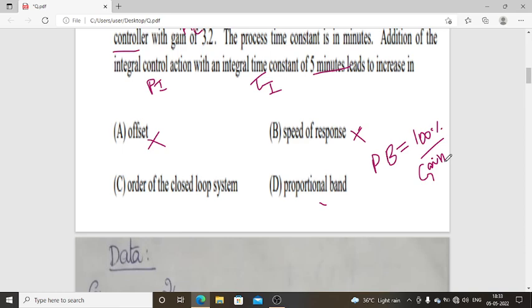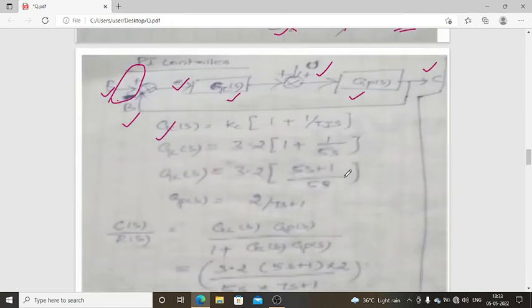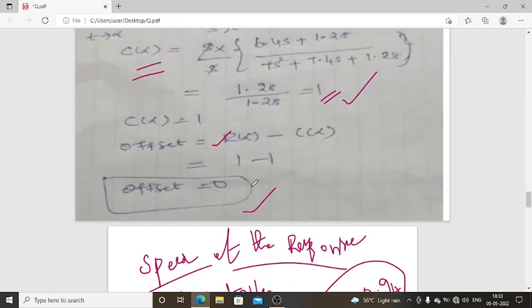The general concept: integral control action is widely used because it provides an important practical advantage, the elimination of offset. The offset value for the PI controller is equal to 0. To understand why offset is eliminated, in order for the controlled process to be at a steady state, the controller output P must be constant.